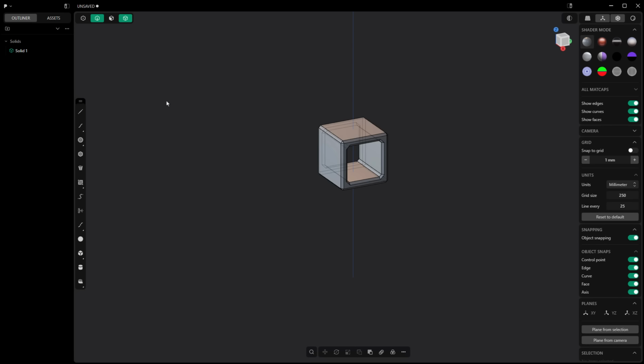You can also hold down the Shift key and then manually add or remove additionals from that selection. So if you don't want everything to be able to be selected, for example, if you don't want bodies, but you want the control vertices, the edges, and the faces, or let's say you just want edges and faces, you can hold down the Shift key and use those numbers to do that as well. So that can be very helpful.